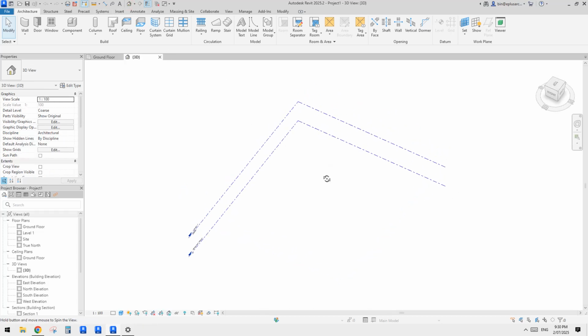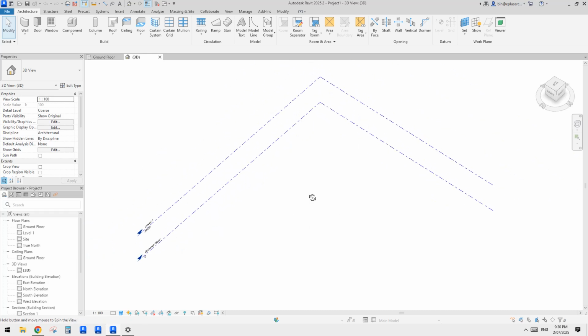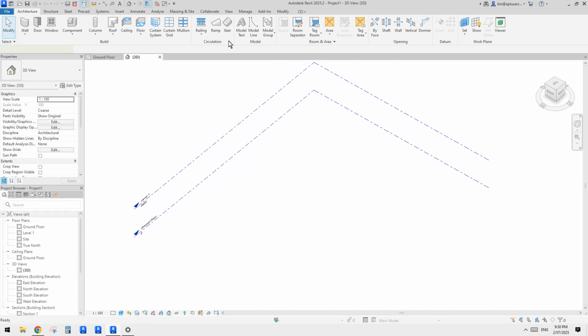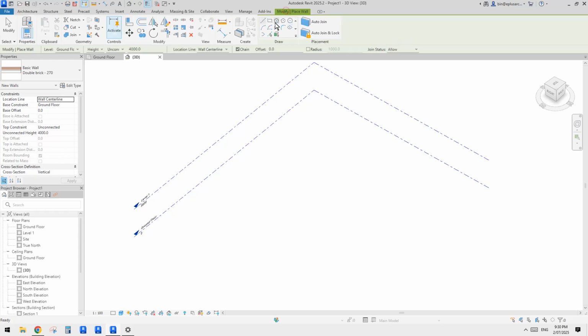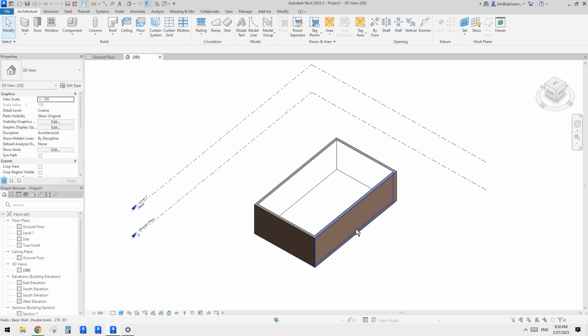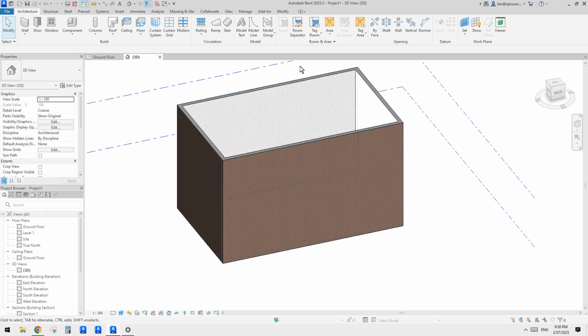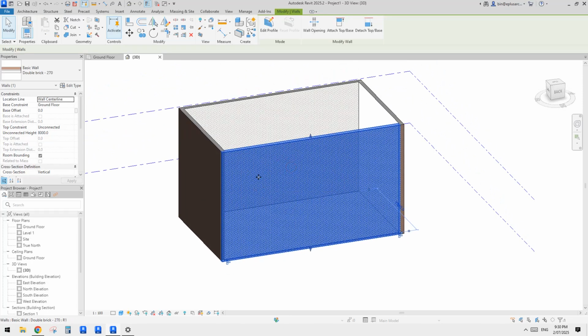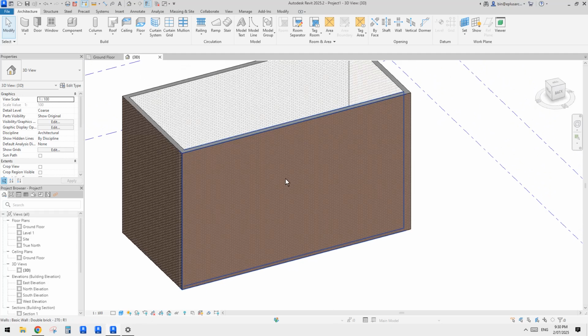Okay, so first let's create a project. So we start with this architecture template, or maybe just place some wall. So WA, just place some wall. Flip the wall. Or maybe make a meter. Okay, so now we're going to place some beam system onto this wall first.